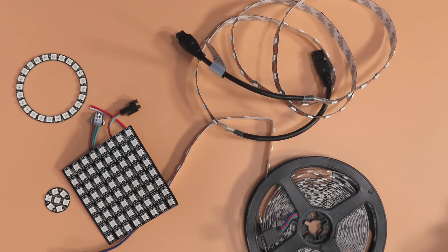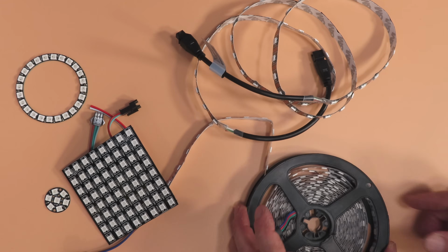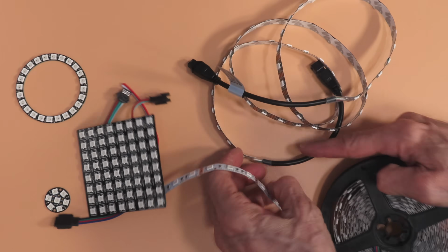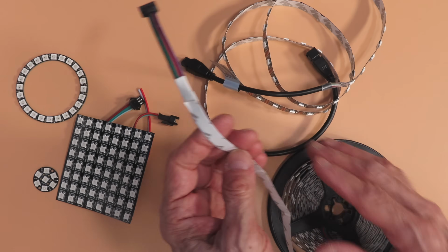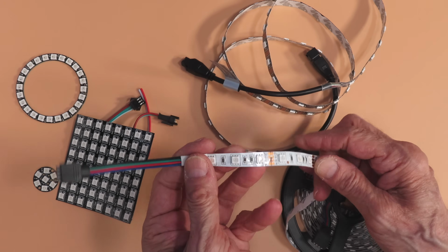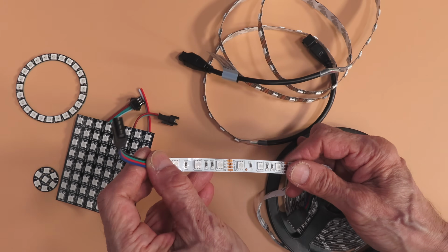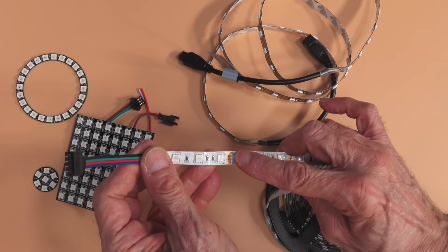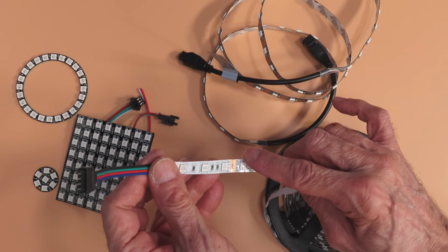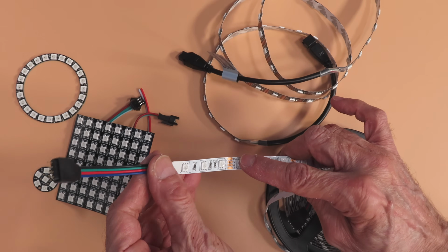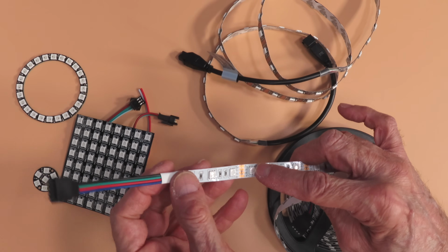And here we have a selection of LEDs, all sorts of LEDs, and one thing in common with them all is that WLED can drive every single one of them. Now we're going to start off over here with a non-addressable LED, this one over here, and this is just an RGB strip, so you can see it's actually got 4 conductors, the red, green, and blue, and the common conductor, which I think is actually positive, not negative on these things.